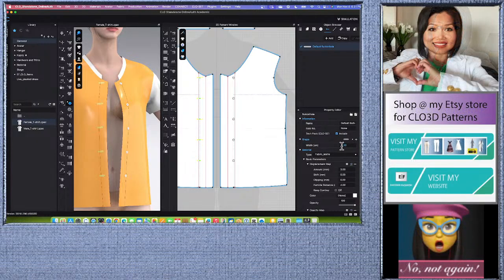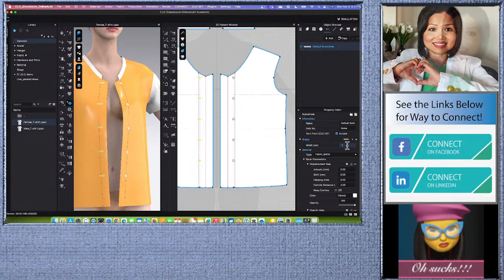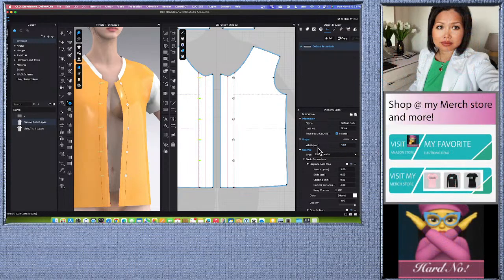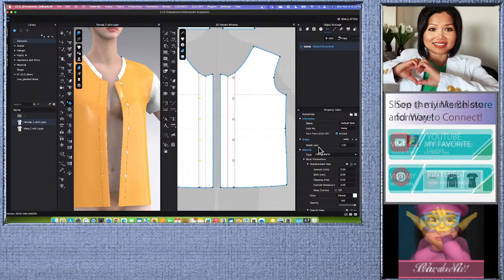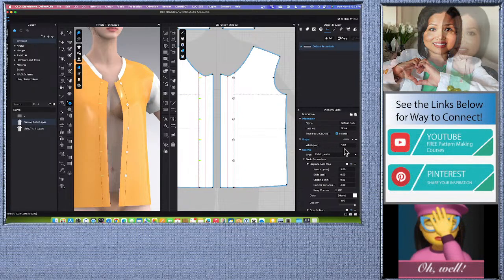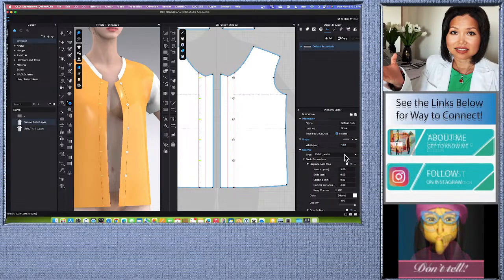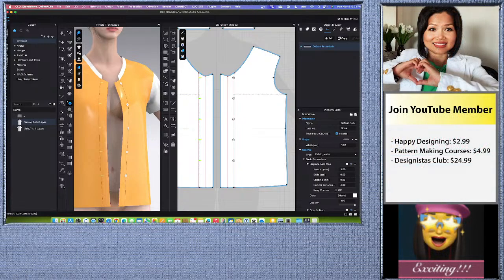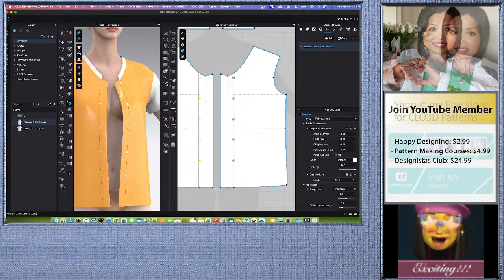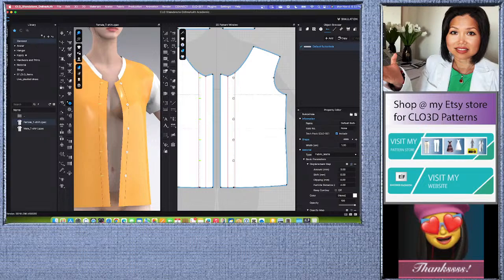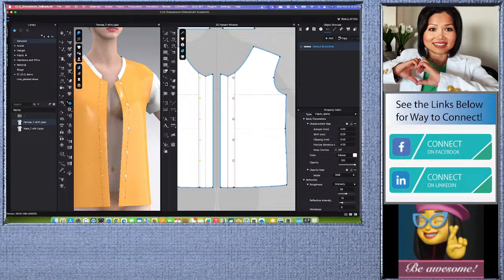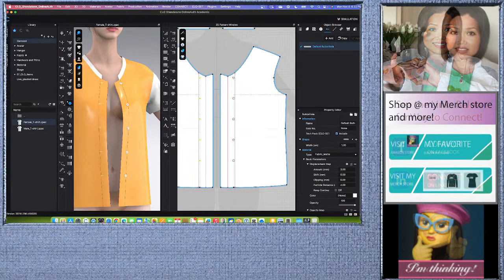And over here, we want to change the size now. 1.2, and press return or enter on the keyboard. If you look right here, this is in centimeters, so 1.2 is 1.2 centimeters, and that's what we want. Alright, once again, if you want to change the color, we can change it down here, but we're not going to do that right now, because we will find out later what color we're going to use. Alright, if I look right here, I do not see the rotation of the shape.